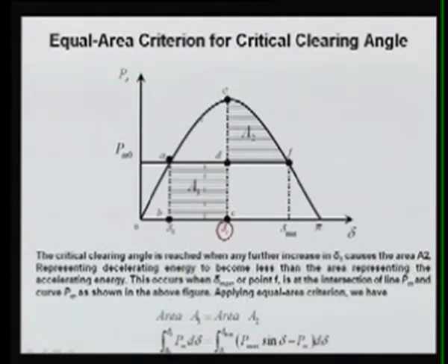So the accelerating power will always be less than the decelerating power, and the system will be stable. Determining this critical clearing time is very, very important.